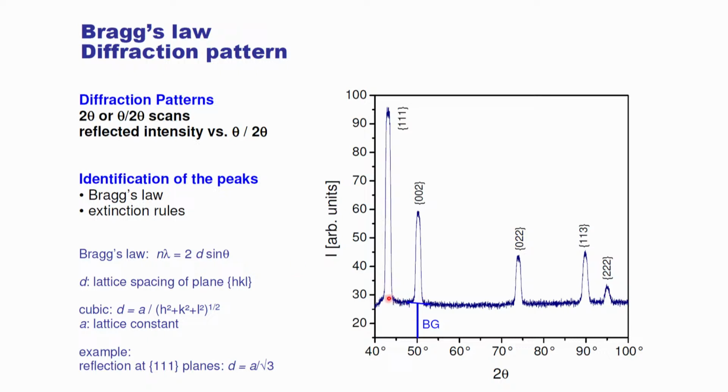So then we can come in and we can say, based on this crystal structure, we know what Bragg's law is. We're going to talk about these extinction rules, which means which planes are going to diffract in which different crystals. Sometimes we call them selection rules, sometimes extinction rules. So which planes actually are going to diffract? And so if we know we have a FCC crystal where if all HKL are odd or all HKL are even, then we're going to get diffraction. Then we can assign what the diffraction is to each of these peaks, if we happen to know what crystal structure we have. If we don't know what crystal structure we have, then we can play some games and figure out exactly what crystal structure it is. These patterns are unique for different crystals.